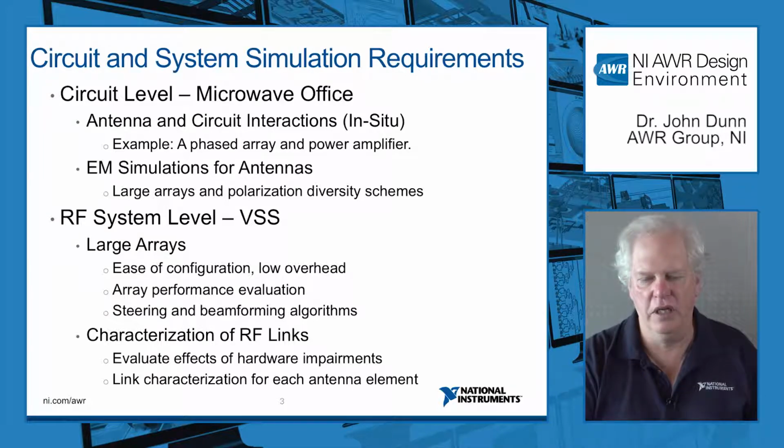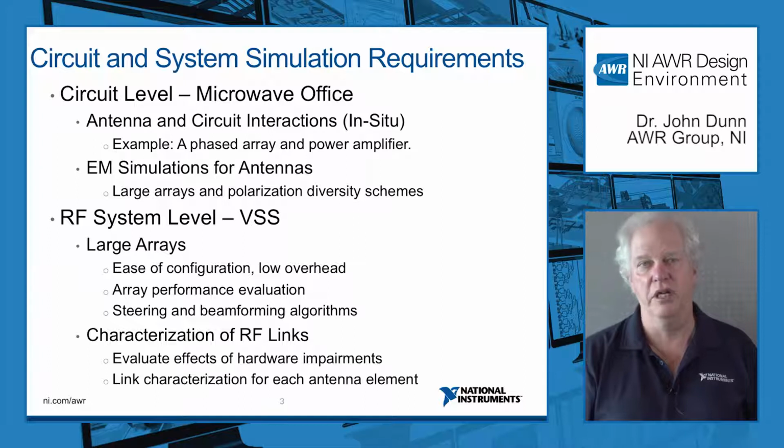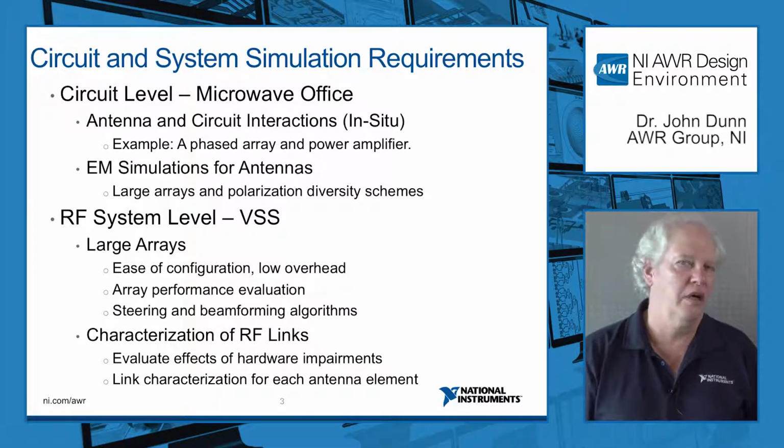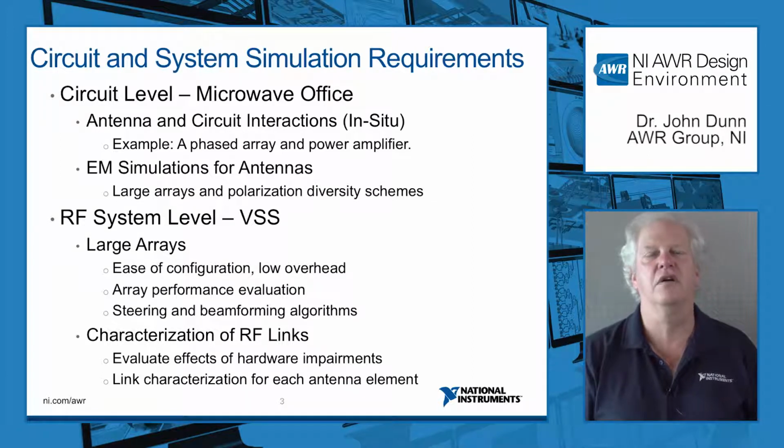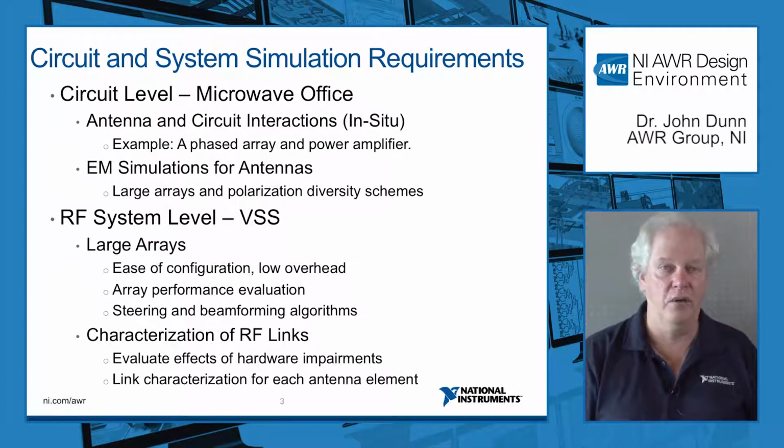In a nutshell, as we get into it, here's the problem. You have an antenna array, and of course you're going to steer the array by changing the inputs, the power into the inputs, their power level and the relative phasing, and this is what steers the beam. This is how we steer an antenna beam. Well, that power is coming from power amps, and the trouble is the power amps are affected heavily by the load impedance, which is the same as the input impedance to the antenna port, and so they affect each other, the power amp and the beam.